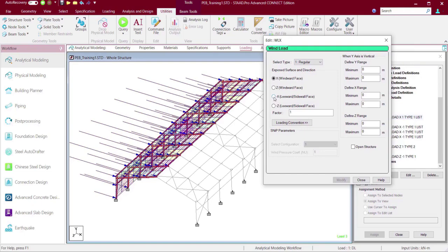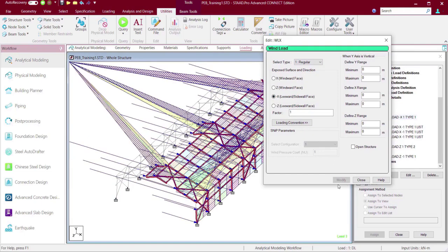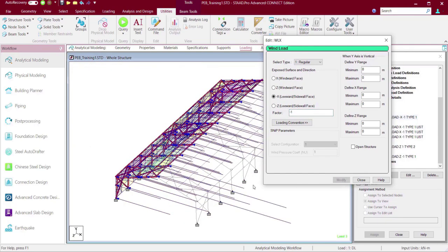There is immense internal pressure compared to the external pressure. So due to this pressure difference, the roof would experience pressure hitting from inside the building. You can simulate this by using the leeward option.